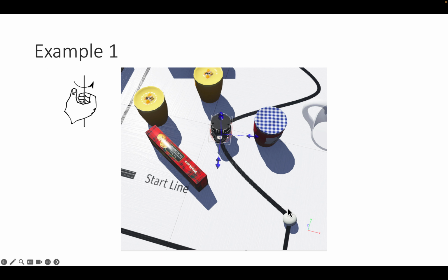And it's minus 50 degrees because the x-axis is here and clockwise is the direction of negative rotation. So we write down minus 50 for the arcus tangens. The orientation of the robot itself is minus 80 degrees. So minus 50 minus minus 80 is plus 30. So we have to turn by 30 degrees. The direction of positive rotation is counterclockwise, so plus 30 degrees will give us a left turn from the perspective of the robot and will turn the robot toward the ping pong ball.